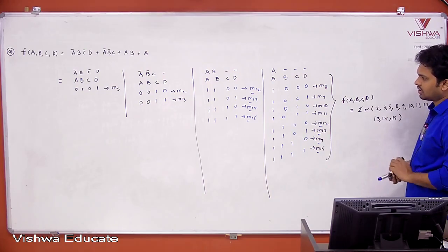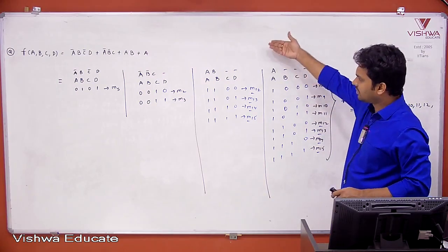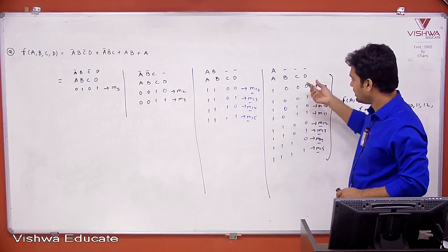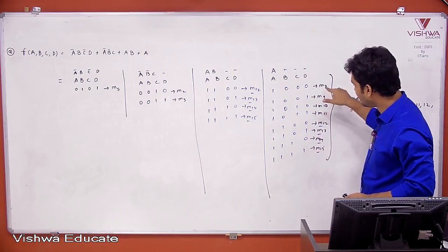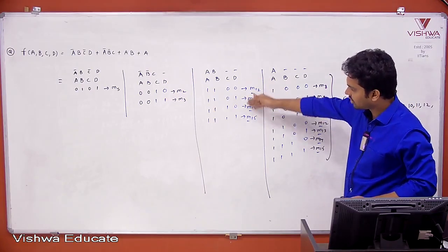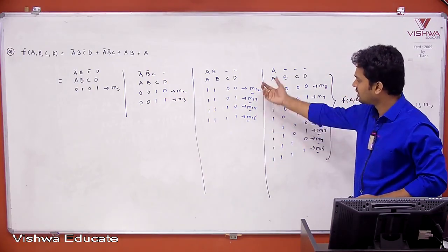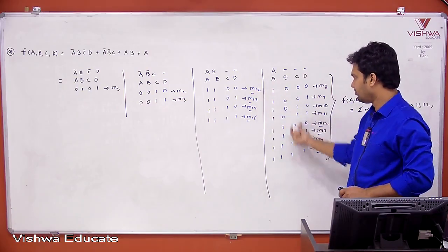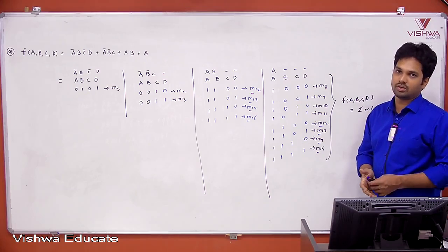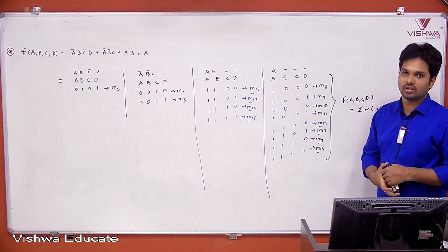Okay. So you can understand, you can go by that method or this method. This is the easiest way, because for explanation we have taken all. Here, all zeros to all ones means directly you can say minterms 8 to 15. Here it starts with 12, ends with 15, all numbers between them. From an exam point of view, you can do it very fast here. So this is the way to convert your SOP to canonical SOP. Another way for this. Okay, copy it.